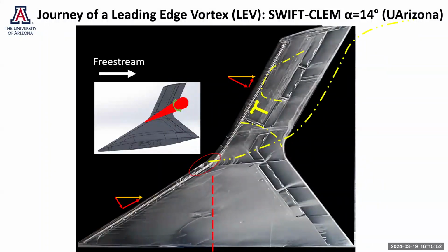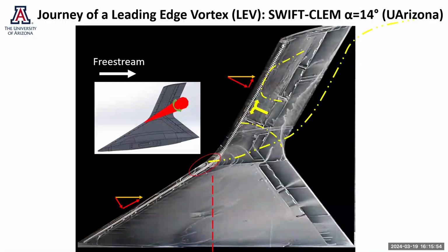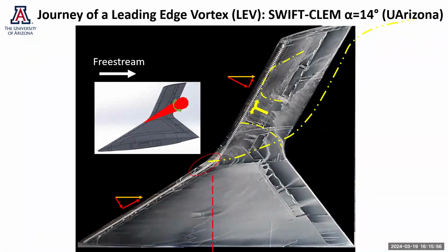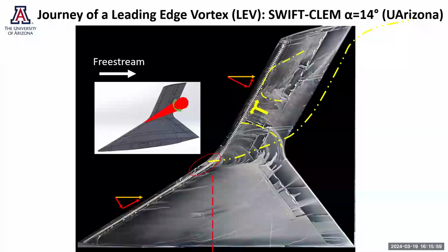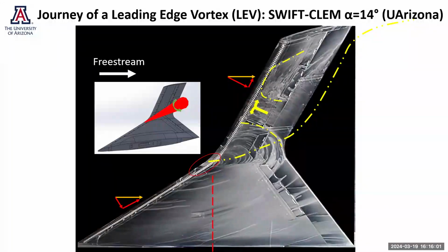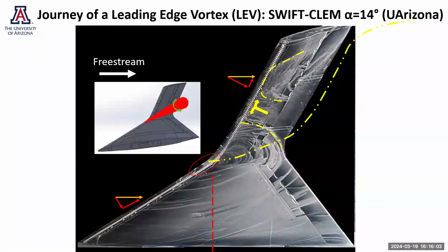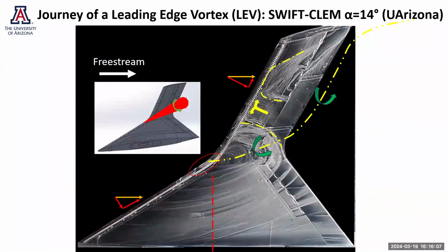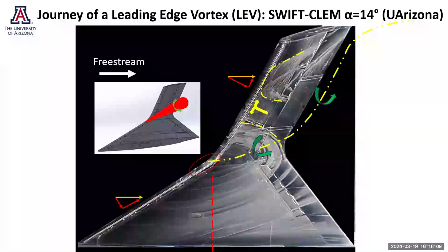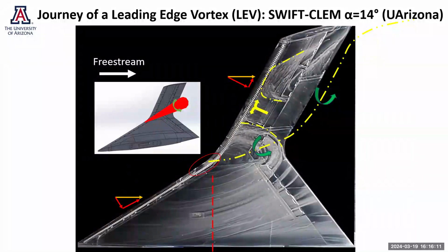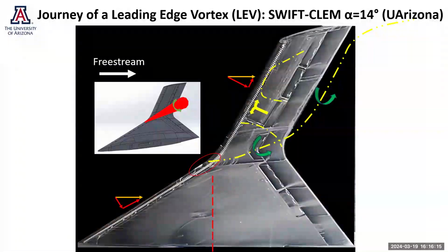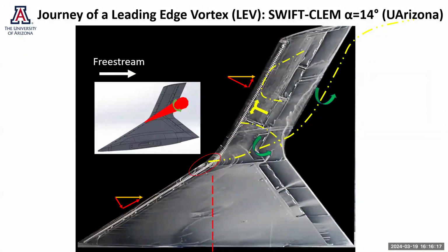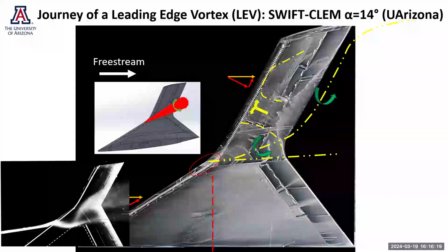Now, for the vortex that lifts off, like this 3D vortex, in order to have such flow reversal on the outer wing, the trajectory of this vortex liftoff is hypothesized to be marked by this yellow line with the anti-clockwise rotation, which will impose the flow reversal on the outer wing. Okay, we will elaborate more on this later on.